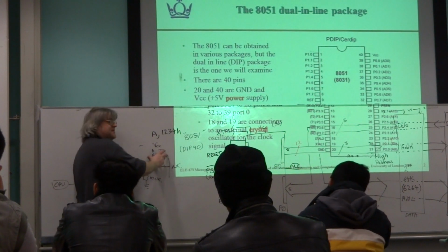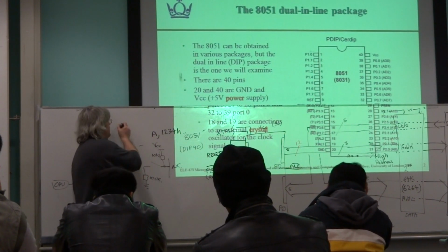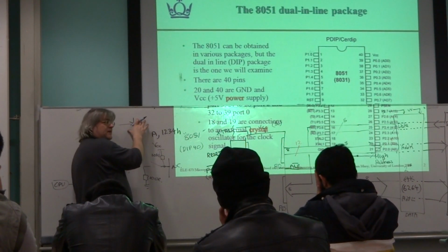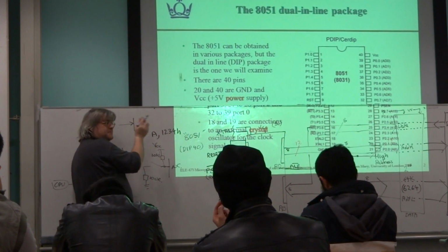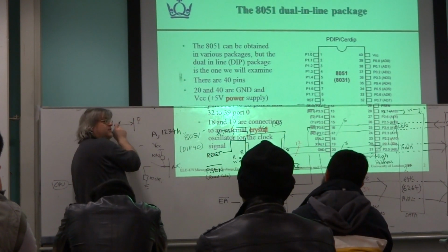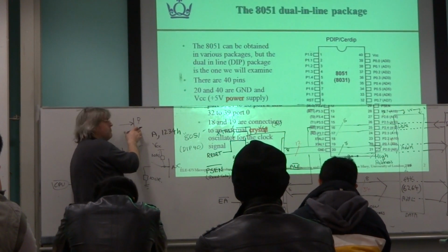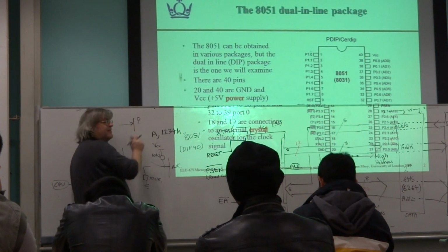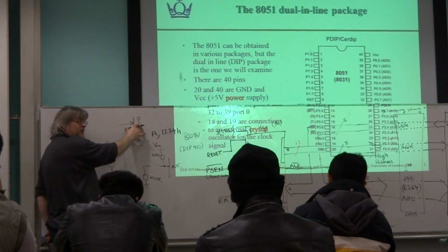So, pull-up resistors are there to stop things from floating. Because if I have a pin being used as an input and I haven't connected it to anything, and I sample it, who knows what it might read that as? Now, in some devices, they have an internal pull-up resistor, so that even if you don't connect it, when you read it, you'll read something meaningful. But not all integrated circuits are made that way, and some of them don't have anything. If they don't have anything, you really don't know what's going to happen when you read it.